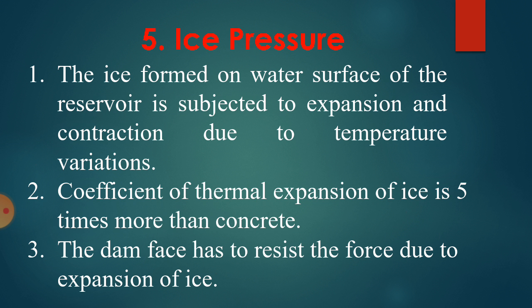Now the next force is the ice pressure. The ice formed on the water surface of the reservoir is subjected to expansion and contraction due to temperature variation. The coefficient of thermal expansion of ice is 5 times more than that of concrete.